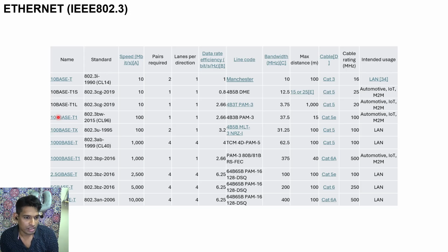what happens is that the relays will report to SCADA with significant latency. It will either stop completely or it will report with significant latency. Packets will drop. There is no sufficient bandwidth for GOOSE. 100 base T does not provide sufficient bandwidth for GOOSE reliably and for client RCBs to report to their client. So when you're connecting relays in a D-Link switch, you have to keep in mind there is no sufficient bandwidth. You can take DR, you can extract all those things, but there is no sufficient bandwidth for multicasting. There is no sufficient bandwidth for MMS.